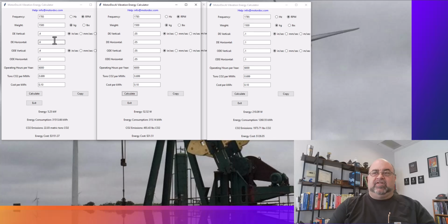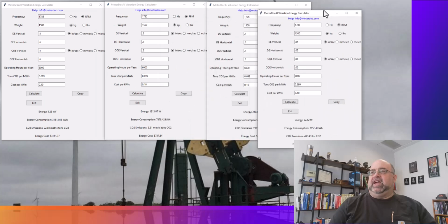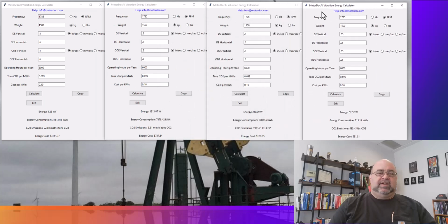So I've gone from unbalanced, so very poor, where the bearing life, let's say if my bearing life would have been 20 years, would be like 3 or 4 years. This brings it up to over 10 years without any lubrication issues. So that's basically the purpose of this, to demonstrate that as I continue making improvements, I can reduce my losses.